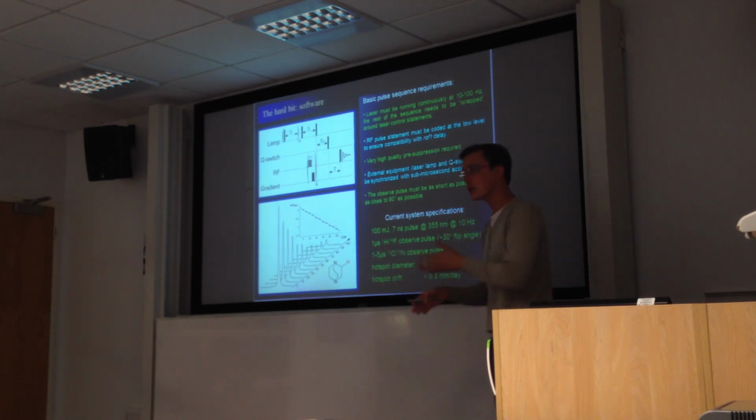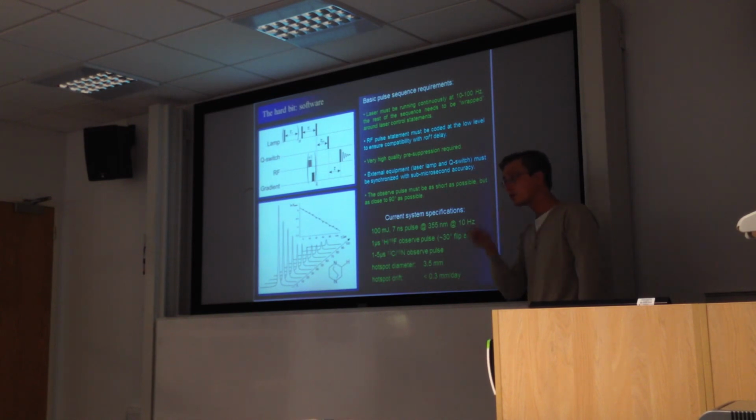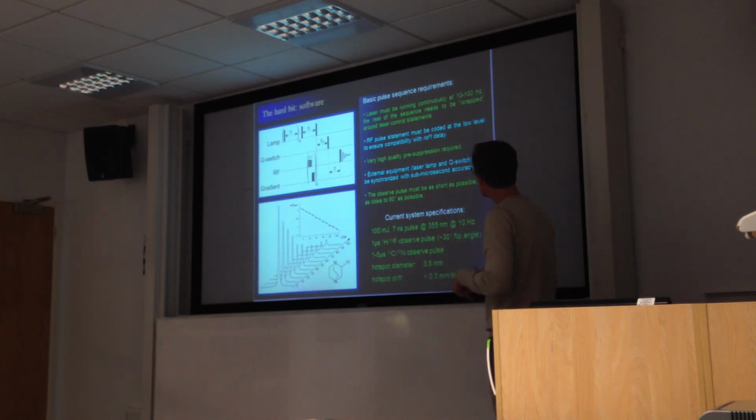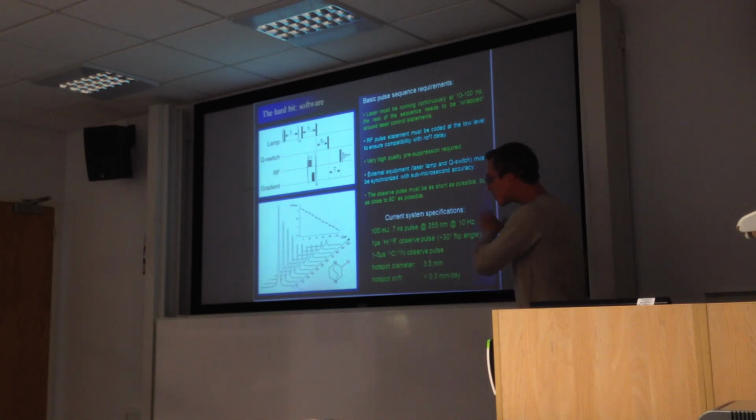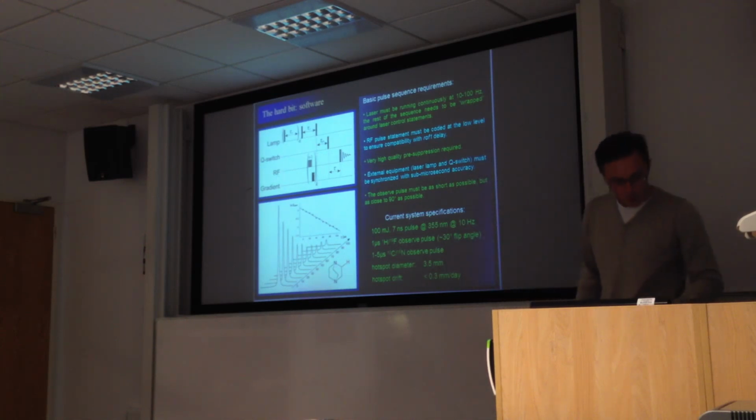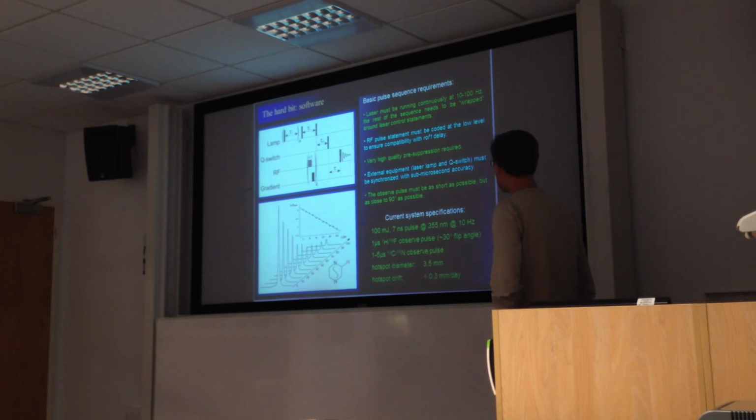so those 2 extra TTLs and the various latencies involved had to be mapped and programmed around, particularly seeing as Varian spectrometers have got this ROF1 and ROF2, which are not directly user editable, and so we had to go into the headers. Thankfully, Varian programming language is C, and they supply the actual headers, so I had to go into the header, and when Varian has its ROF1, after the pulse, the gating delay, I think it is called, I had to stick the laser control statement before the gating delay in the Varian header, rather than the actual pulse sequence that was going ahead. So it is a bit of tweaking on the programming side there as well.